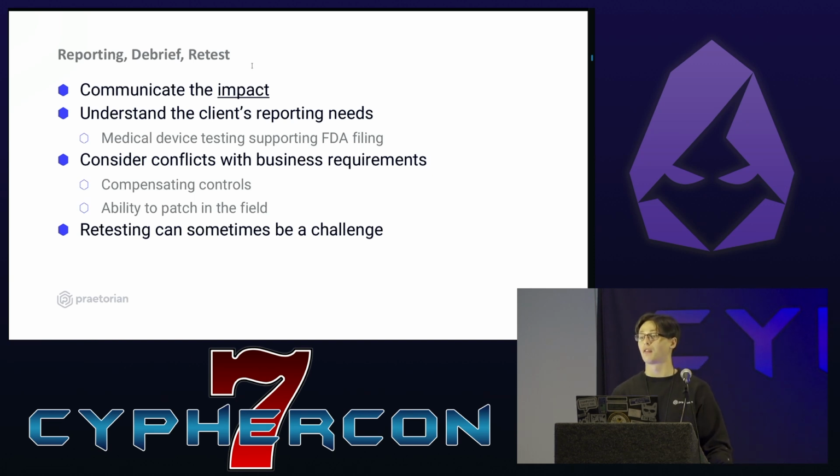And retesting can also be a challenge because for a lot of these devices, they might be deployed in the field and not have an over-the-air update mechanism. So for some of these devices, a firmware update might be a technician going to the field to update it. Or if it's a hardware vulnerability, there may be no fix they can do in the field, and it's just permanently vulnerable until a new generation comes out.